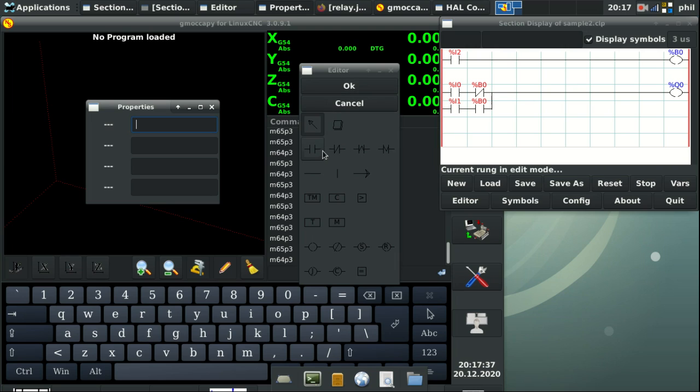If I wanted to add a spindle inhibit or something like that, I could add a logical I/O into this string and make it so that it can't fire until all of those status inputs are met. So it's helpful in a way because, again, it allows you to create safer logic.